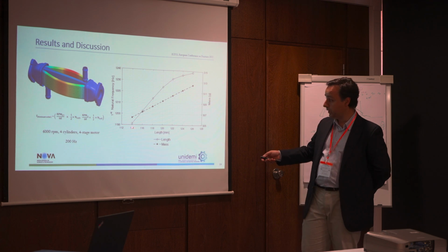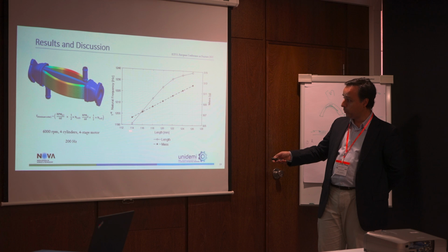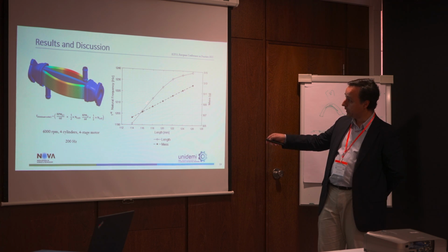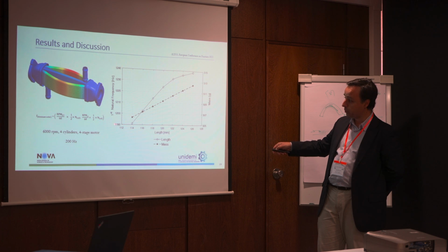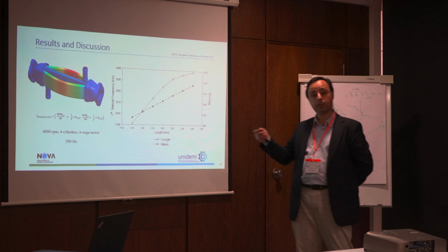As you can see here, we have placed in this axis the fins length from 114 to 126, and we can see that the variation of the first natural frequency will be like this, and the minimum frequency is 1190 Hertz, which is very far away from 200 Hertz, which will allow us to conclude that the system will not enter in resonance anytime.